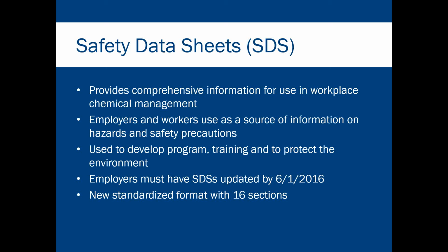In the supplemental information, there was the OSHA format, basically the GHS format for the safety data sheets, if you would like to go through and follow along. It has detailed information, but we're going to hit some of the highlights. So the first one, section 1, is identification. It's going to include what is it, who made it, and who do I contact.